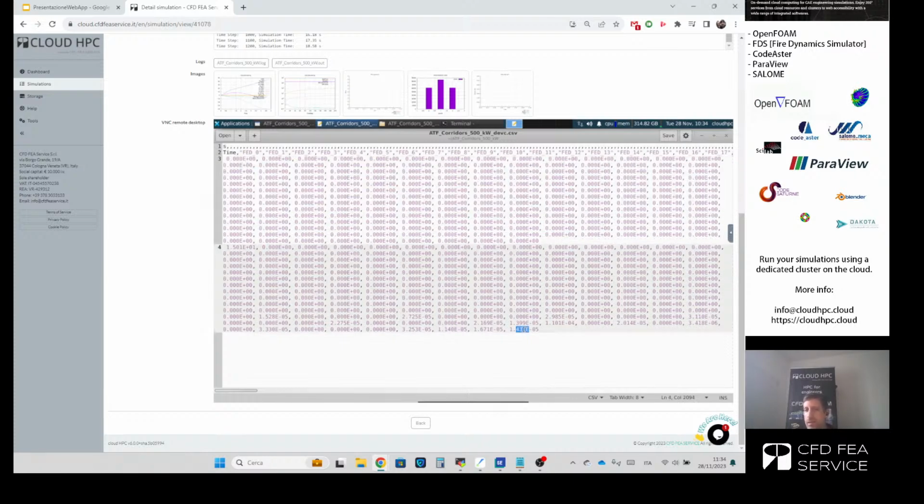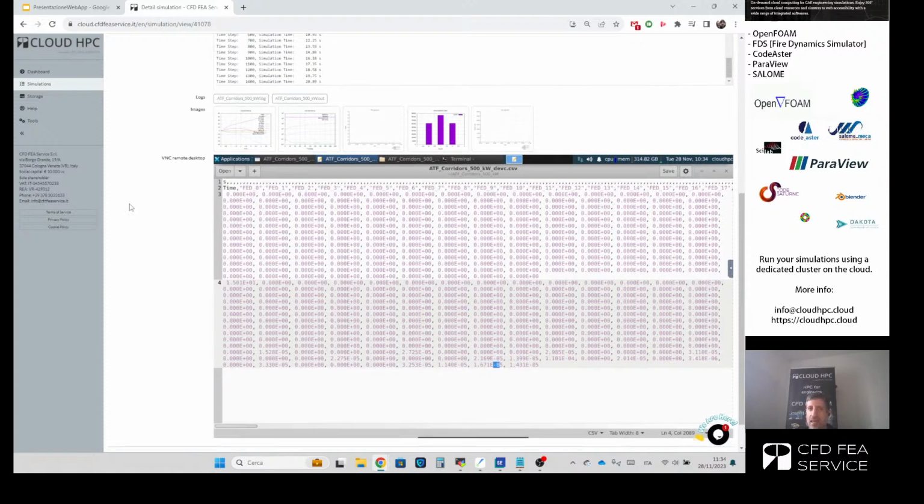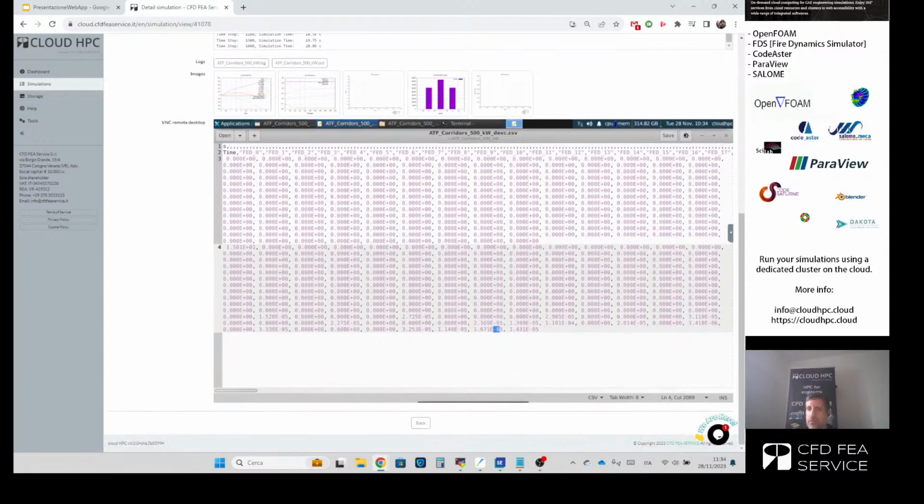Since there is a little amount of smoke, we have some devices getting 10 to minus 5, which is 0.00001 in terms of FED. The limit is actually 0.1. Okay, so we are about 3 or 4 orders of magnitude below the limit. So it is still acceptable at this stage, at this moment, to have this level of FED. But it depends on how the simulation advances, what's going to happen for this analysis.